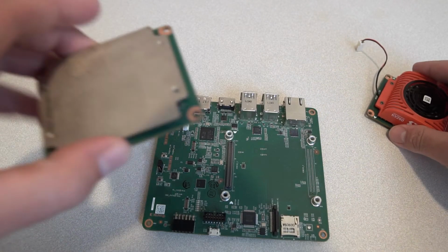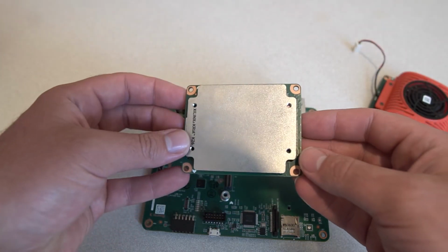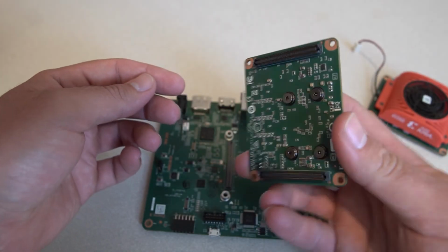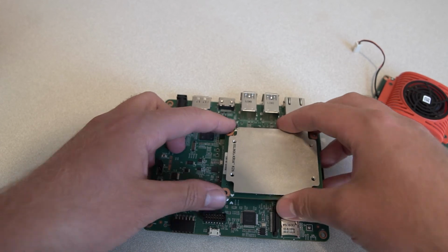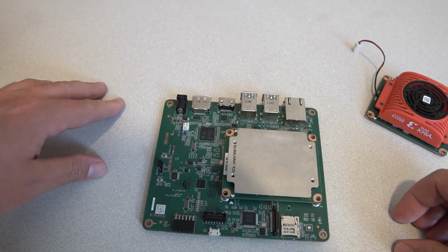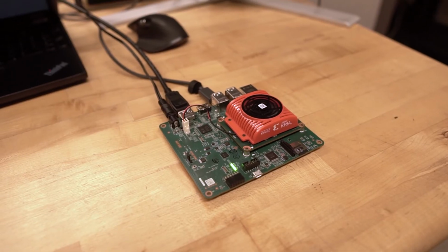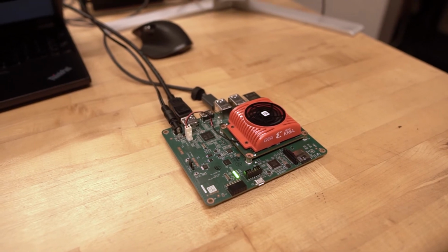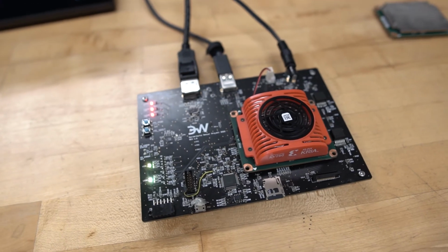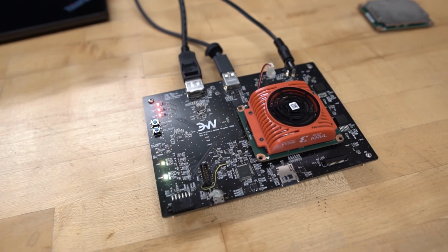On the hardware side of things for this project, we decided to go with a Kria SoM as our main processing unit, which has a couple different CPU cores and then an FPGA built into it. We decided to use this card because then we can create a carrier card around it, which has all of our inputs and outputs that we need to plug into it. So we started with the dev kit and then basically broke that down into only the inputs and outputs that we need for our project.